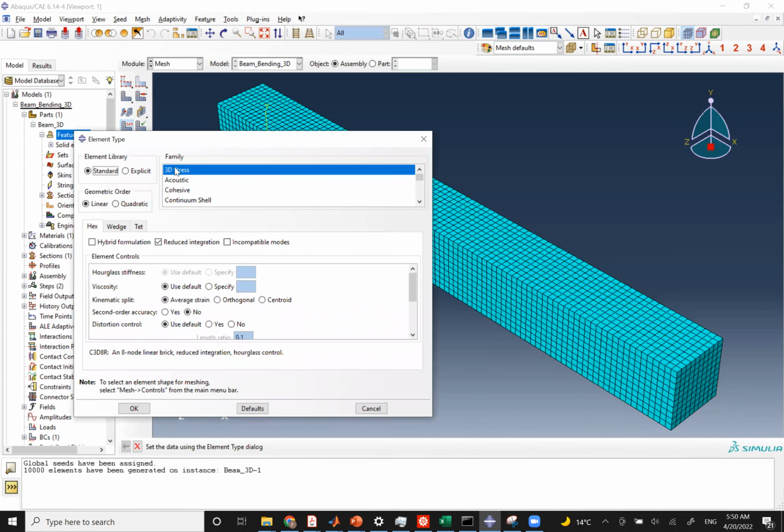Since we're applying the load, there will be a bending moment, and there will be a generated shear on the pipe. The regular element may introduce what's called a shear locking phenomenon, which occurs due to limitations of the element.